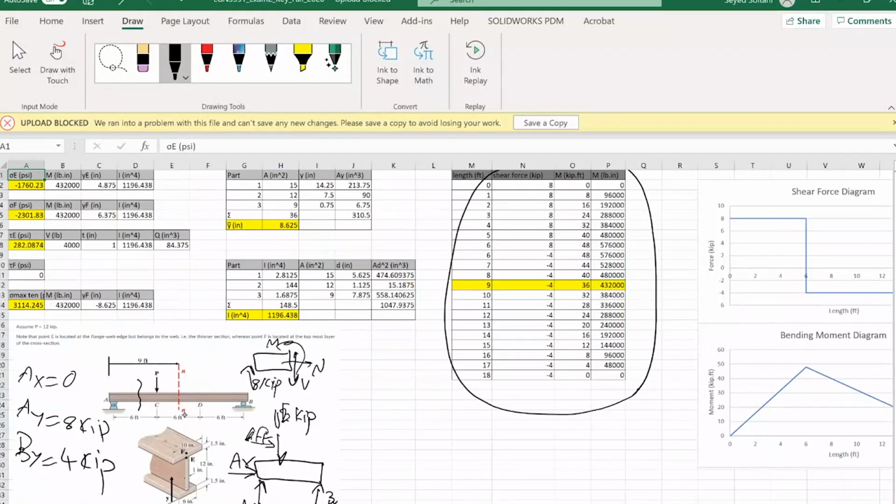Now, if you take a look at the right segment, the segment CB, let me see if I can draw right here as well. And again, cut a section and then use the right piece now. I have 4 KIP here, and then the shear force right here, and M. I established the balance of forces along the Y direction, and this time around, I'm going to get a -4 KIP over the segment CB, or in the segment CB.